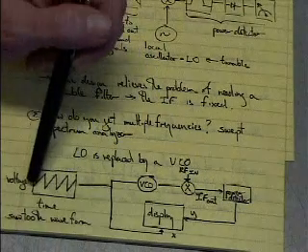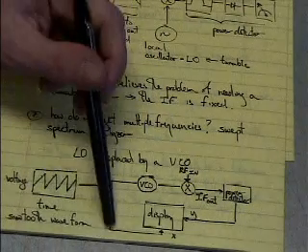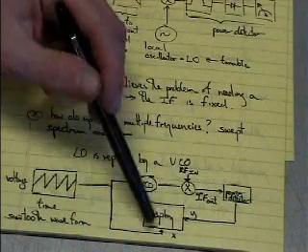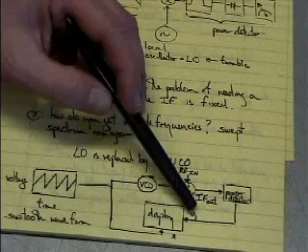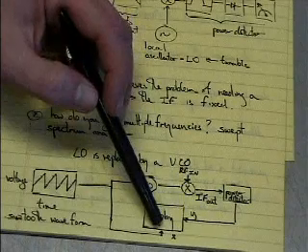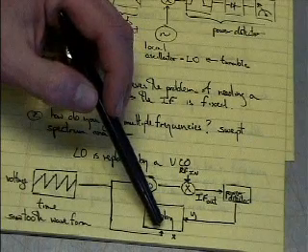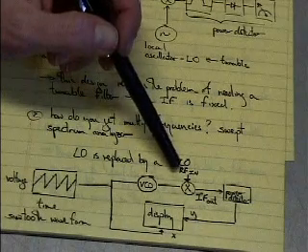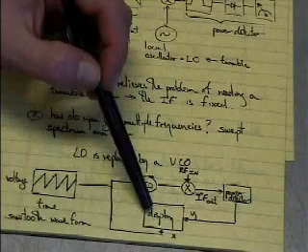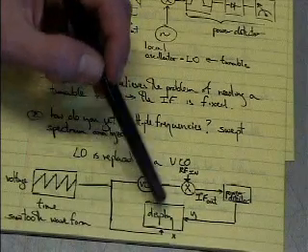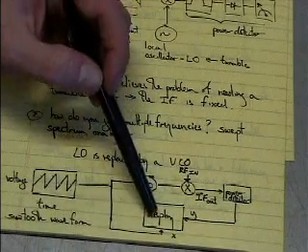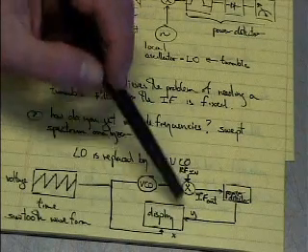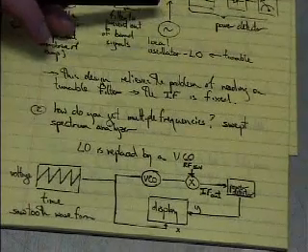At the same time that you're ramping this voltage up, you're also ramping it across this display. So you're doing kind of an XY plot, where you're going to get the Y, which is the power, and an X, which is a function of the frequency. Okay, if this is varying linearly, this output's going to be varying linearly in frequency. So you're basically going to be able to plot the frequency that the VCO is at any particular time, and the power that you're measuring at that particular time. Okay, with some offset, but that's not really that important.